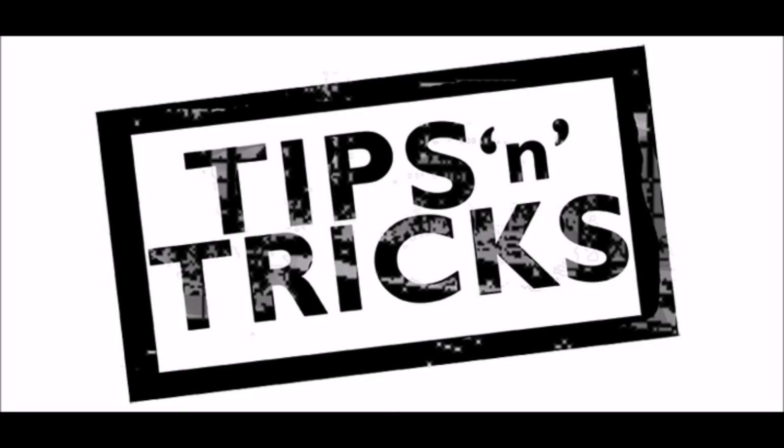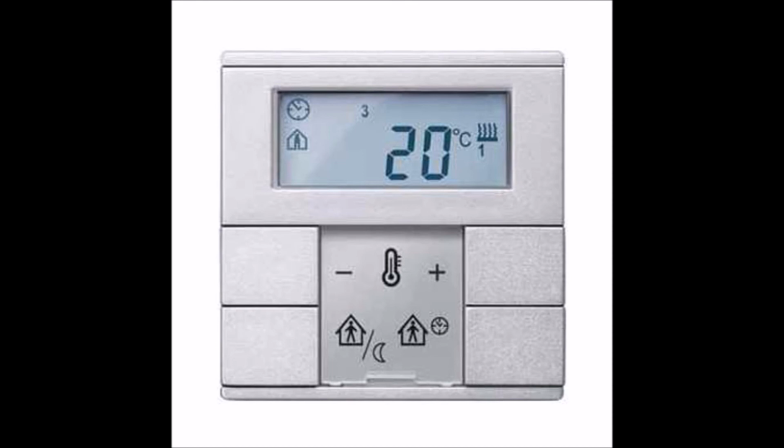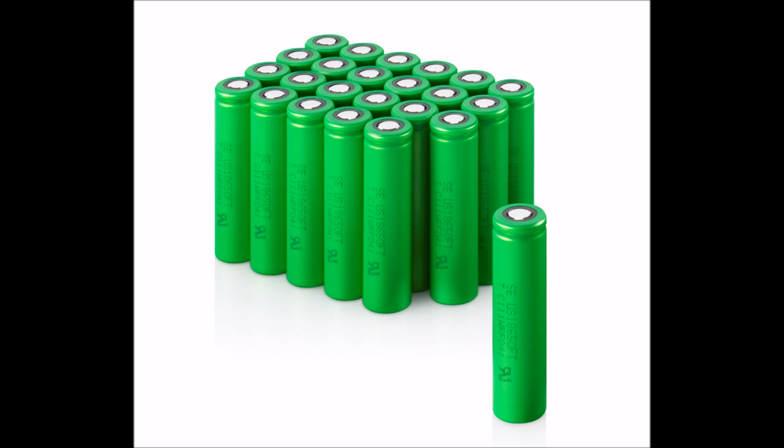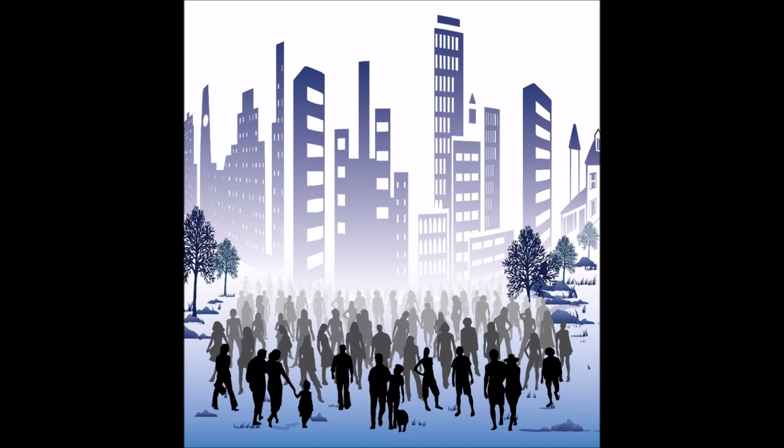Some tips for extending lithium-ion battery life are to keep them at room temperature, and to also avoid completely discharging them. For extended storage, you should discharge them to about 40% and then store them in a cool place like a refrigerator. But don't store them somewhere like a freezer, that's too cold. Hopefully, in the near future, lithium-ion batteries will continue to improve and have a positive impact on society.